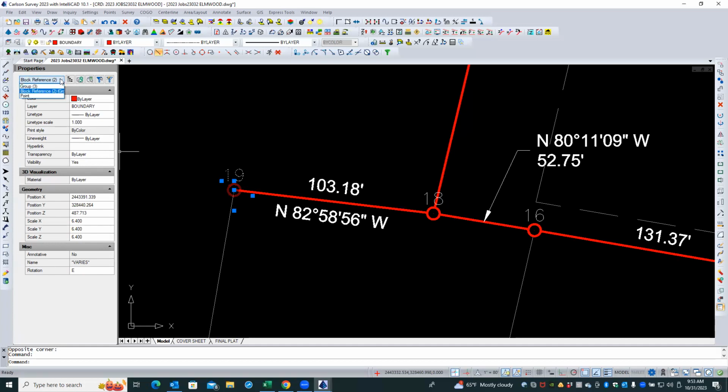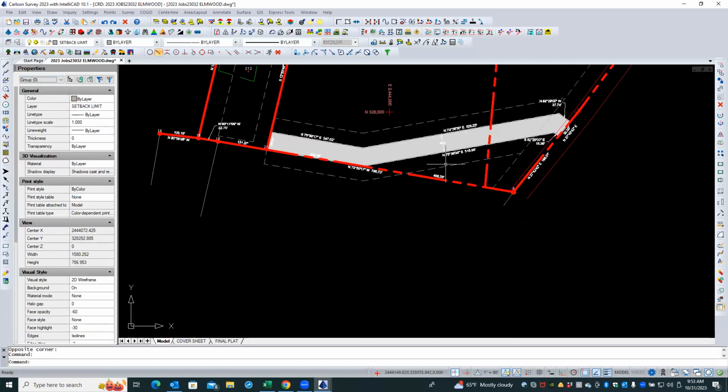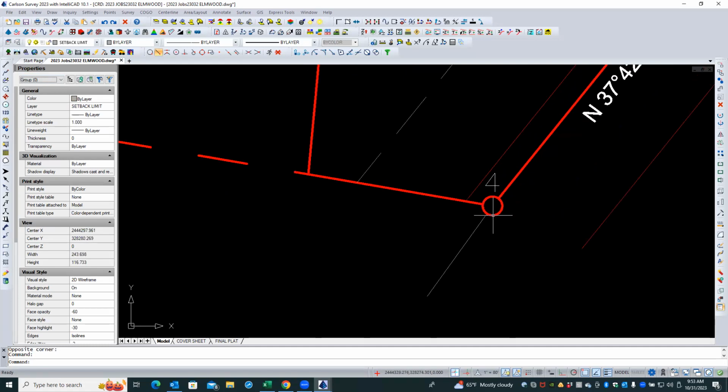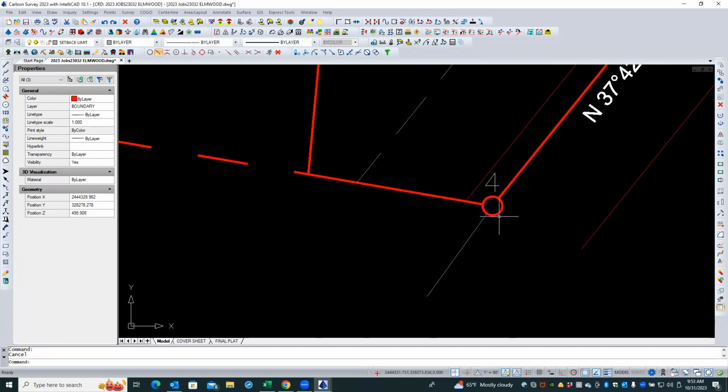See, why does that come up as a block reference and a group, but this one doesn't? I don't understand. Let me see if that used a different, that one already is annotated. That's why. That's why I shouldn't have changed that to 6.4, because it went to try to make it 6.5 inches tall when it plots. So that made sense that way. All right. So that one now says, yes, it's actually annotative. All right.